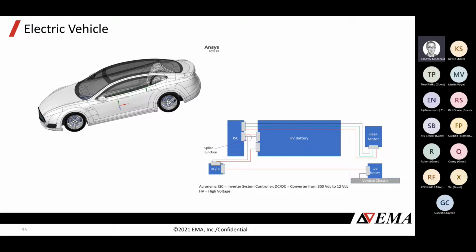Separately from that, we have more autonomy in vehicles, meaning I have radar telling me if there's someone in the lane beside me. And cars are starting to make safety critical decisions based on those sensors. Whenever part of a vehicle becomes safety critical, now it's got to pass EMI EMC, not just by choice, but by regulation. Most governments have regulations for safety critical parts of vehicles. So we don't have a choice. If we don't pass our EMC, our vehicles cannot be sold when they come off the line.